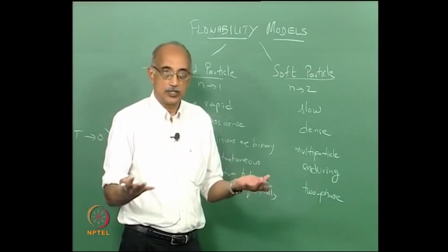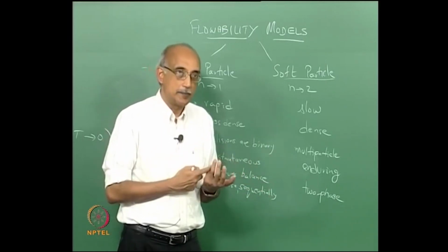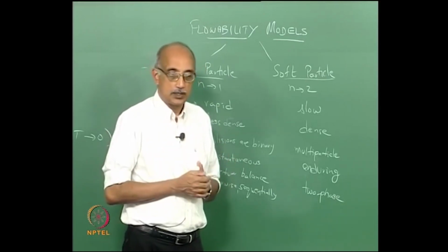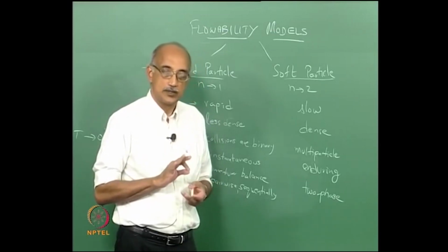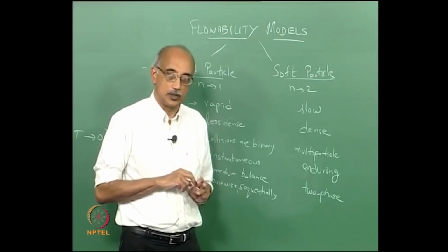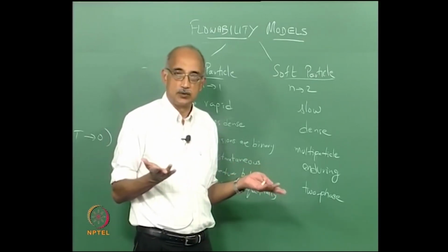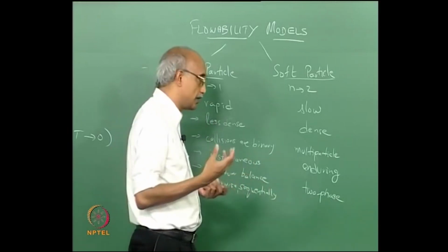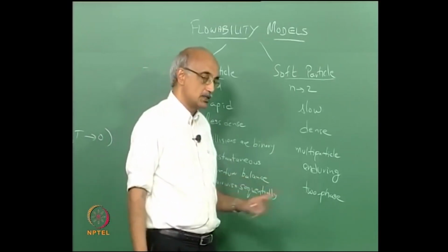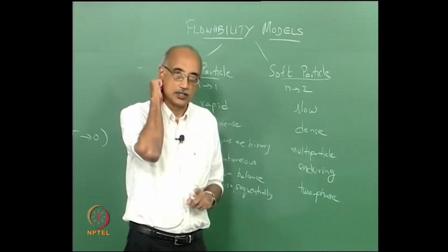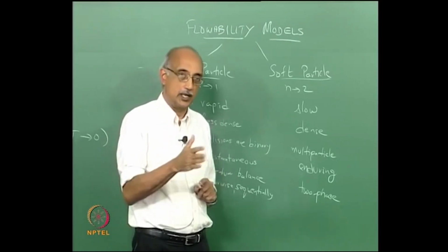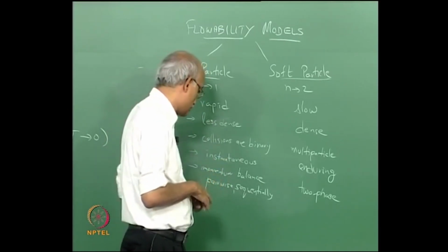What happens to the particles afterwards will completely depend on the direction of impact and also the surface area that's in contact and so on. So, it becomes almost impossible to predict with any degree of confidence how particles are going to behave in this hard particle model. It is more like a Monte Carlo simulation. You assume a high degree of uncertainty and you try to estimate the probability of how these particles will flow, whereas predictions in the soft particle limit can be done in a very deterministic fashion. You have a pretty good knowledge of how this phase is going to flow and behave as a function of time.